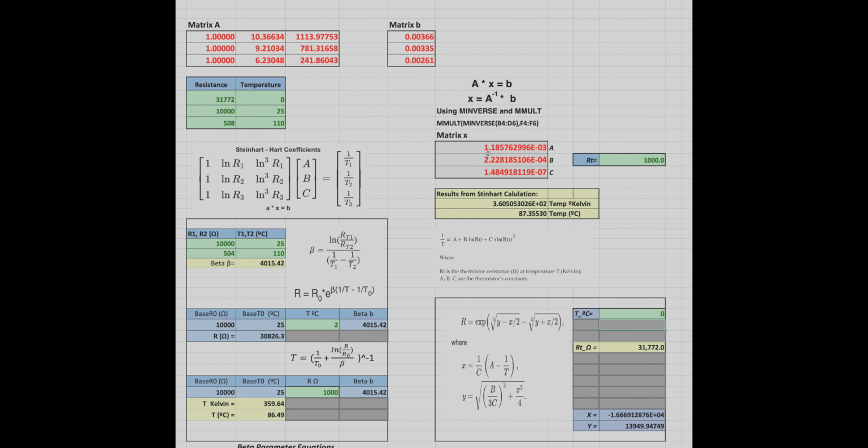RS, RT. So we have RT equals RS times VS over A0 minus 1. And we can simplify that even further by saying, since the voltage is divided in respect to the ratio of the resistances, VS is essentially, in our case, whatever the voltage reference is of the Arduino.